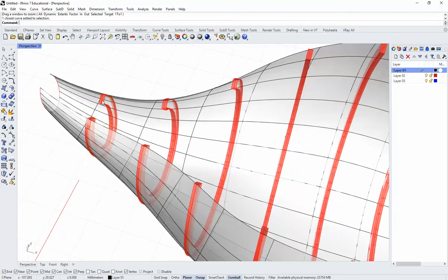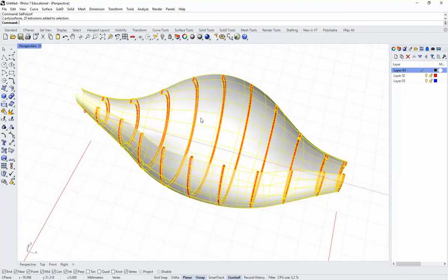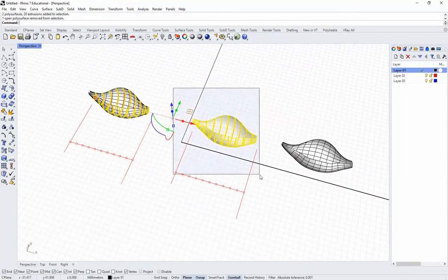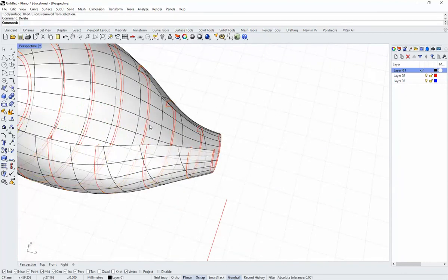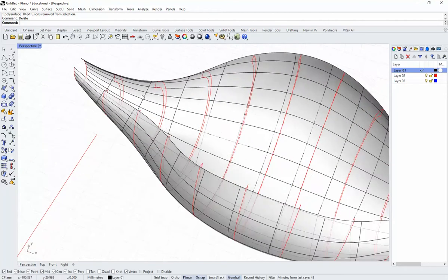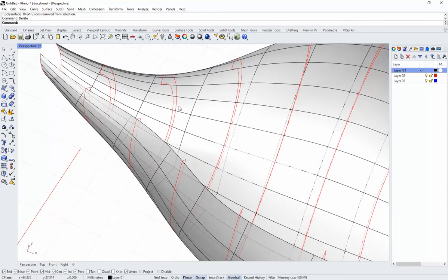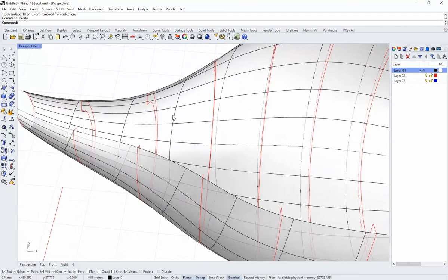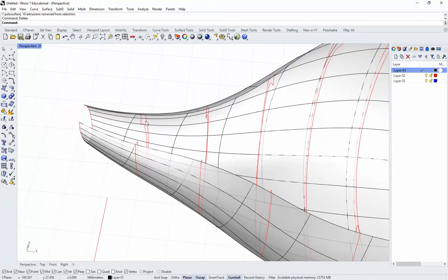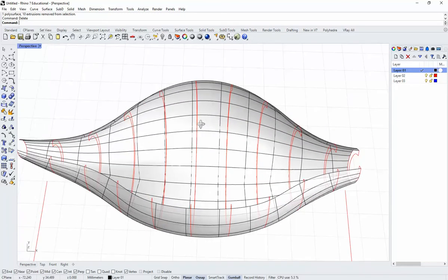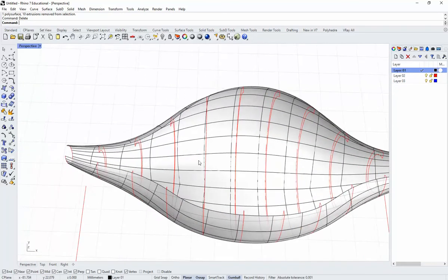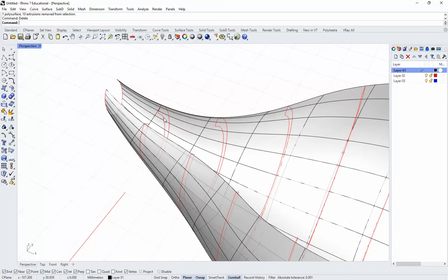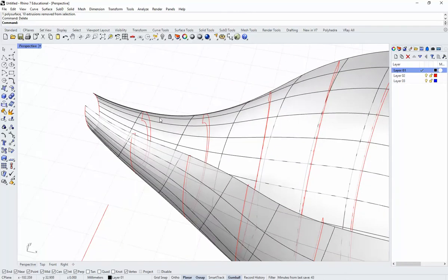I'm going to go ahead and select these poly surfaces here and deselect some other stuff. Just to go back to this point, what we can do is extrude it so that we know for sure that they don't interact with the surface. So we can extrude these inward, and we can extrude on this side the other direction. Okay, so let's try that out, and we'll do this one at a time to figure it out here.